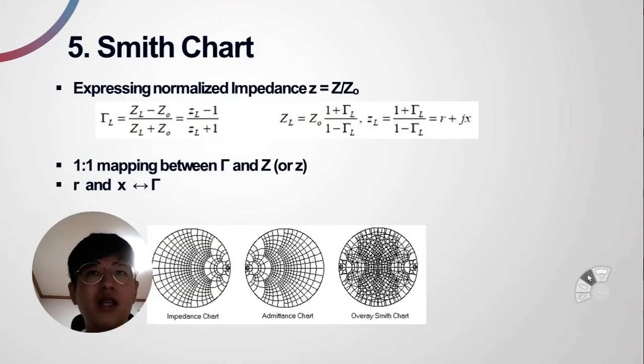The Smith chart is a complex coordinate system that represents real numbers on one axis and imaginary numbers on the other. The reason we need a complex coordinate system is because of the complex impedance. Real numbers are represented by resistance and imaginary parts are represented by inductance and capacitance depending on the sign. The relationship between the reflection coefficient and the load impedance is shown below. If you draw the above equation on the drawing, it becomes a Smith chart as it is.